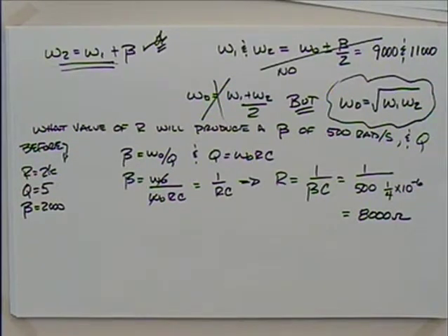So we had to have a fairly large increase in resistance, which is kind of nice because sometimes with series resonance, students will say, hey, I can get a really great filter if I have 5 ohms of resistance. Well, what do inductors oftentimes have a lot of? Resistance. How about your function generator? Resistance. The function generator says right on the front that it has 50 ohms of internal resistance. So we take a great design with maybe 5 ohms of resistance, and we throw in 500 ohms of inductor resistance and another 50 of function generator. What happens to our great design? It starts to fall apart pretty fast. So it's kind of nice that we reduce our bandwidth by increasing the resistance.